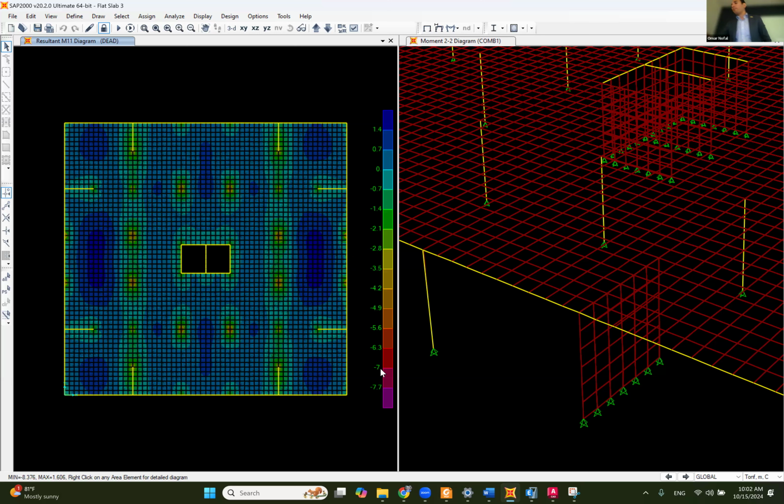Let's say, for example, you have something like the Burj Khalifa in Dubai, okay? So this is actually a shear wall everywhere. All the walls there are shear walls, right? You have beams maybe somewhere around the building. But the thing is, the beams are not going to absorb lateral loads until the shear walls are broken or something, because they're very stiff elements. The earthquake needs to get over with them so that the other moments can be transferred.